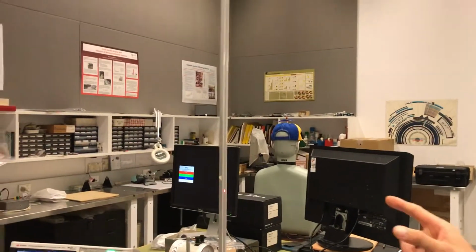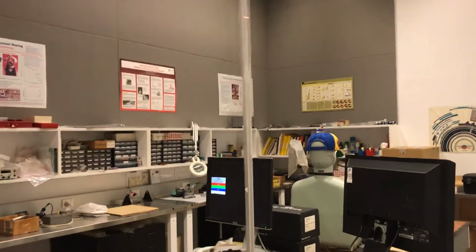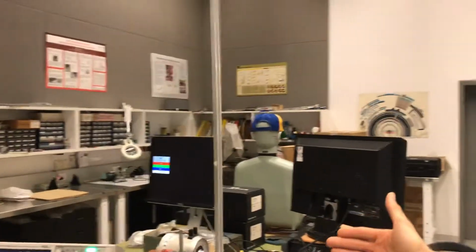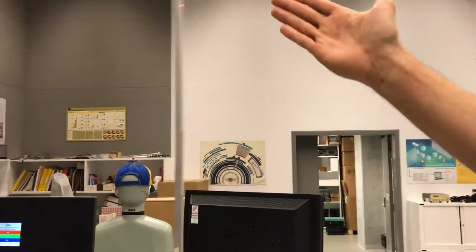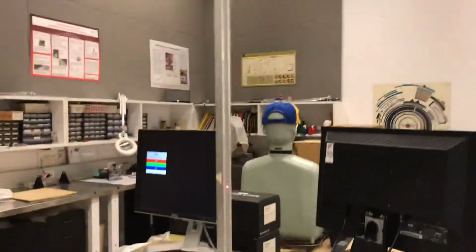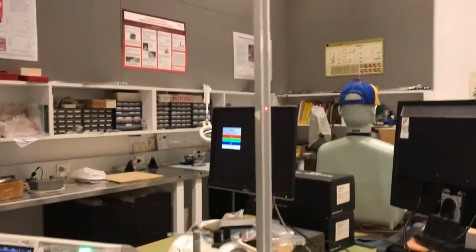So back to our vibrating cantilever, which is being driven with a sinusoidal signal at approximately the first natural frequency of 17.4 hertz. And we can see the laser beam tracing very slowly up and down there, and when it gets towards the top of the beam we can clearly see the amplitude of the vibration. The video sample rate will mean that that's a little bit digitized relative to what you can see with the naked eye when you stood alongside it.